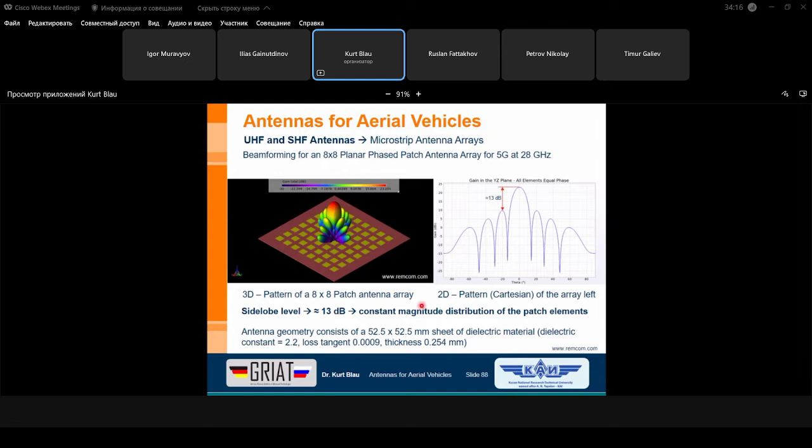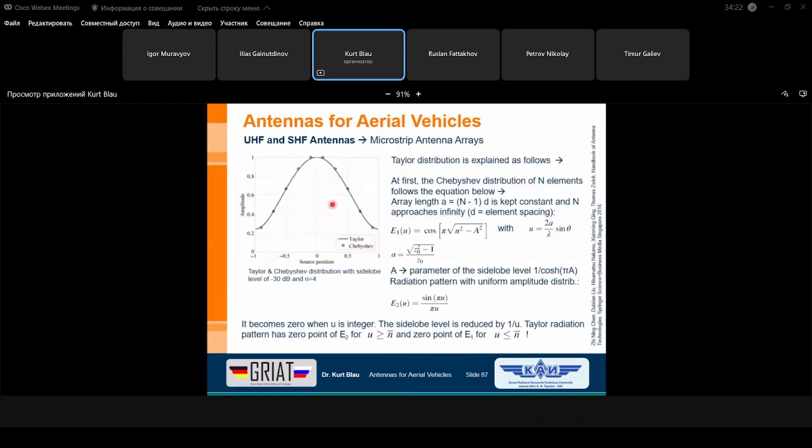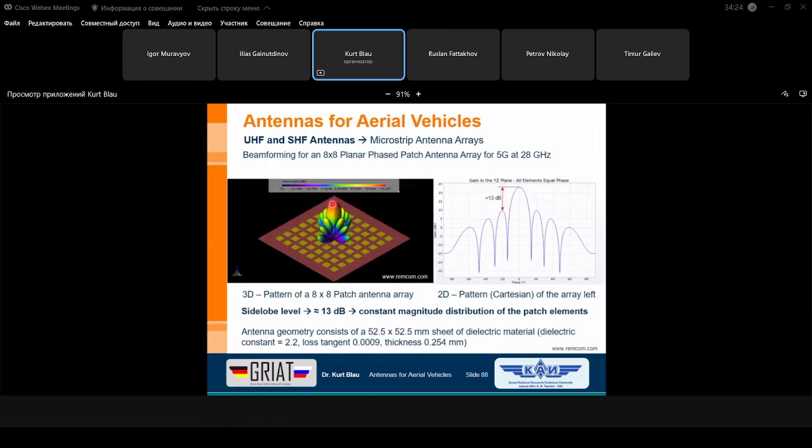By the array factor, you can calculate the gain, as we know, by 64, which is 2 to the power x, and 2 in log scale is 3 dB, so I have to multiply it by x, coming from the array factor. Okay.